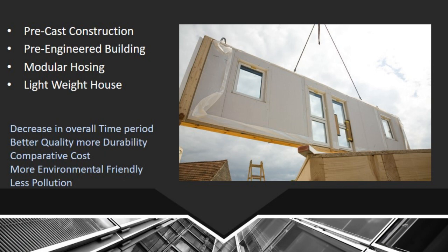So that actually allows you to manufacture things somewhere away from your site, where you are having the proper space. You can manage things like the proper curing time, temperature and all that, and then you can transport it to the site and install it. That sort of technique we have used in all sorts of infra projects, like metro projects, bridges, flyovers, and in railways also. So that is one of the approaches.